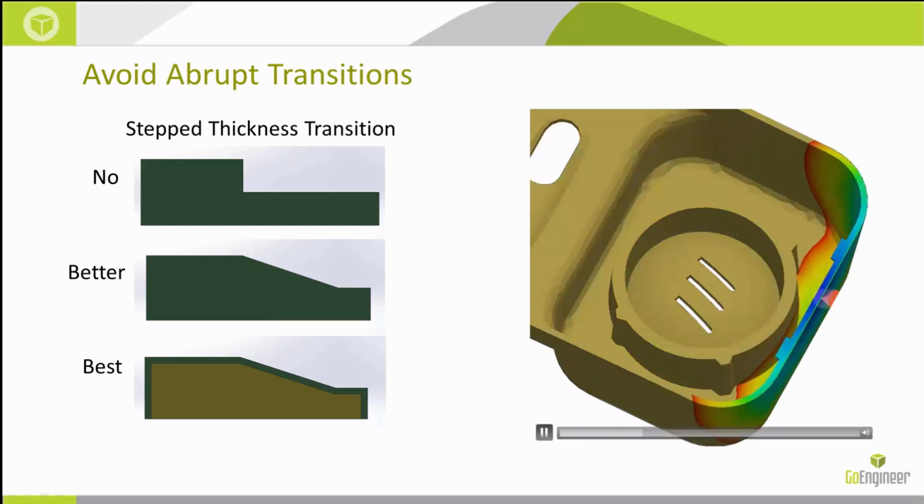If we look at this flow video showing this thick wall section around this earpiece, you see the material wrap around and create this hole down in the bottom. Basically, that's called race tracking. That happens when the plastic hits the thicker section. It'll actually flow through the thicker section faster than the thin sections, and it causes flow hesitation in other areas. Molten plastic flowing inside of a mold cavity is always going to take the path of least resistance.